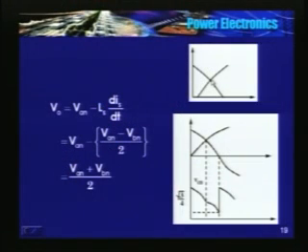So just see here, at this instant is the point of natural commutation. Prior to this point, this is the load voltage, whether it is VAN or VBN or VCN, doesn't matter. At this instant, both the devices started conducting. Now this voltage is the instantaneous value of this plus the instantaneous value of this divided by 2.